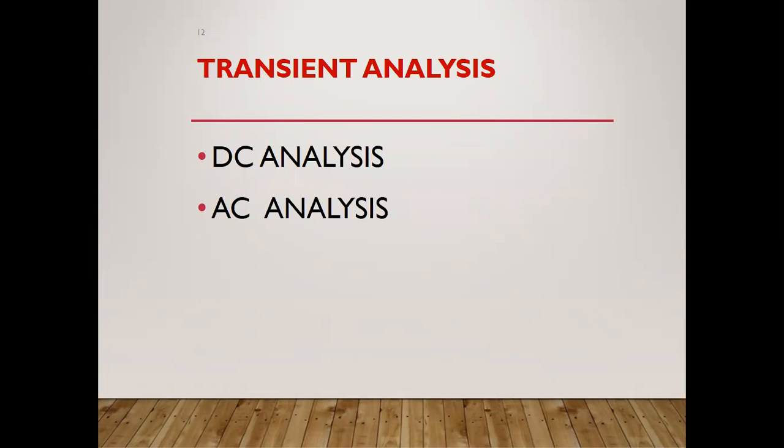While learning about DC, there was no sinusoidal waveform and no impedance Z. We directly measured the voltage, current, and power. So see the difference between the AC and DC analysis. Similarly, while studying the transient, definitely an RLC circuit will be there. If an RLC circuit and switches are there, and we are interested in measuring with respect to time, and my excitation is sinusoidal, then I am analyzing AC. If there is a battery or cell, and there is no variation in the components and switches, then that is the DC form.